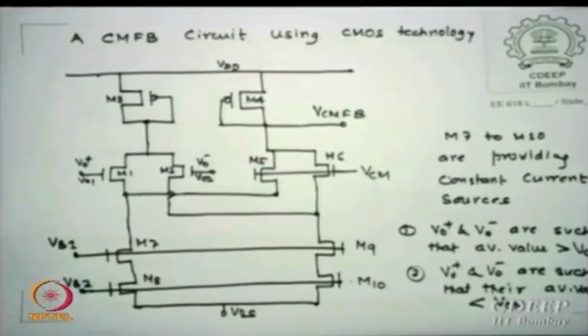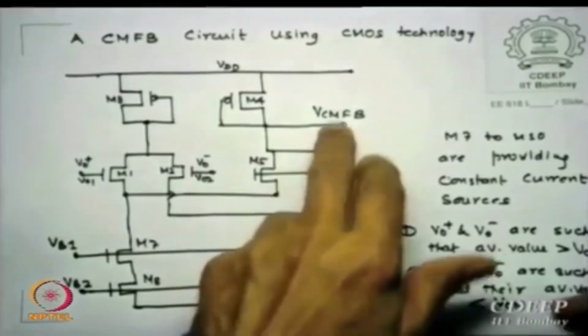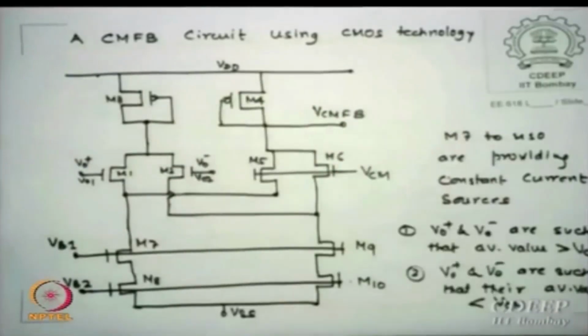Few more things, of course I do not want to say more. These two currents are actually fed to the diffamp stage, what we have seen with the other cascode stage down at the single stage cascodes. So it also divides the current in the diffamp as well as the single gain stage. I have not shown the circuit. These currents can be chosen such that they feed both the difference as well as the cascode stage or gain stage.